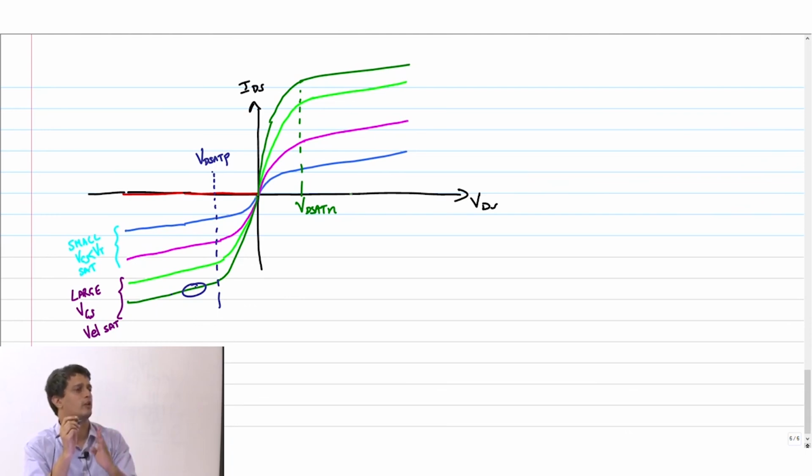It doesn't increase any further, which depends on your VGS value also. If it saturates earlier, then that will basically dominate and you will get a saturation current. Otherwise, you will get a velocity saturated current. Clear? Not convinced? That is VD sat, the velocity saturated drain source voltage, the drain source voltage at which the current becomes velocity saturated.